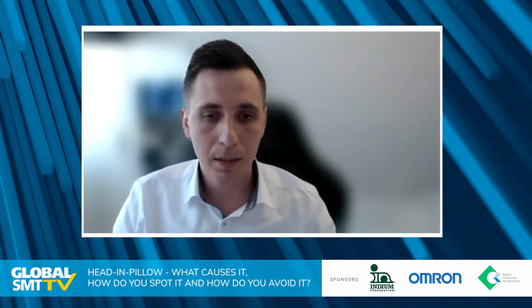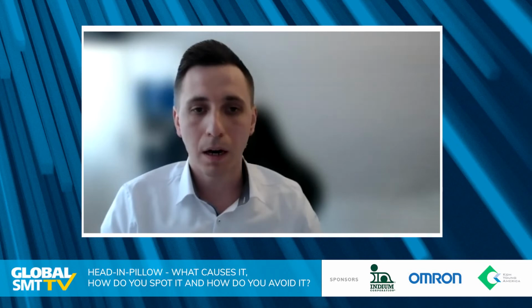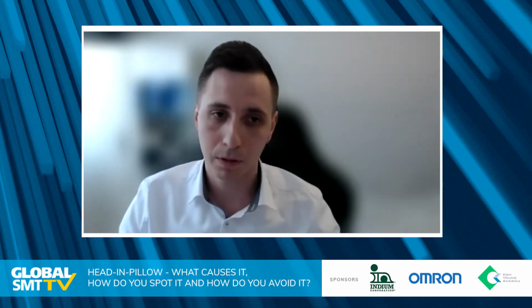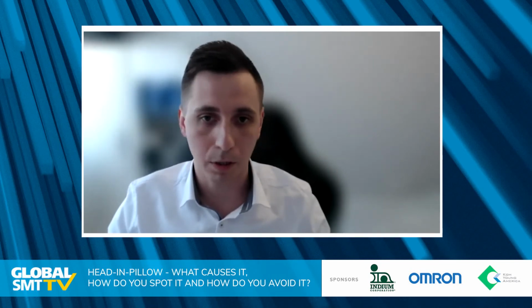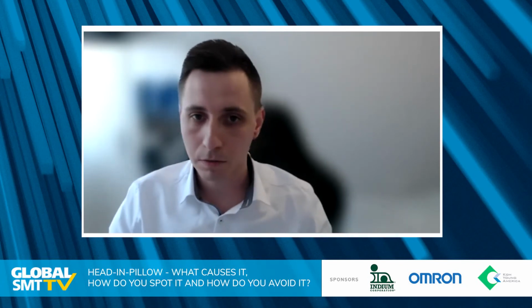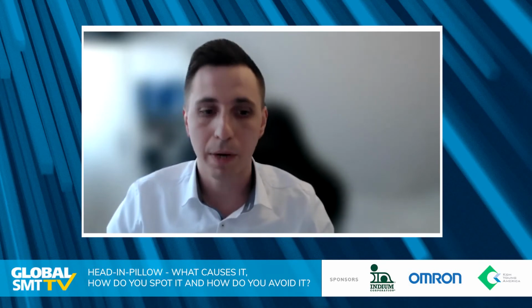Anything to add to that, Piotr? Those are very good examples. So basically, of course, improve the process, improve the materials. But I think what is also important here again is the inspection. While we are modifying our process, I think the key is to have a good, complete inspection. X-ray, of course, for the end product, but also during the manufacturing. Good SPI, pre and post reflow AOI can provide a lot of data where we can apply all those actions that you guys already mentioned.